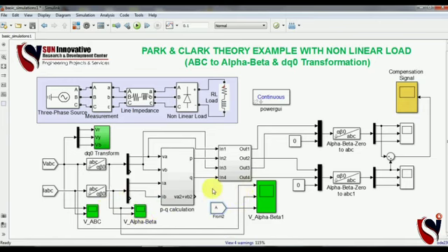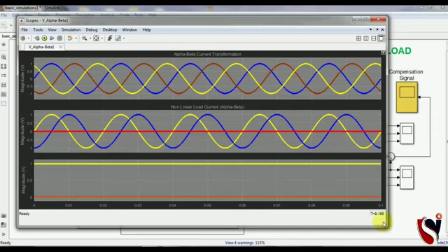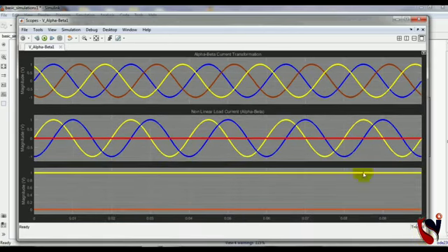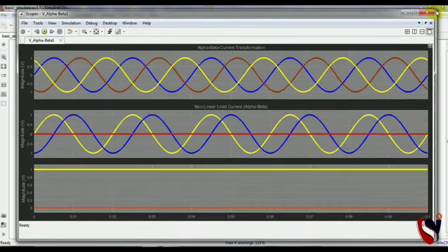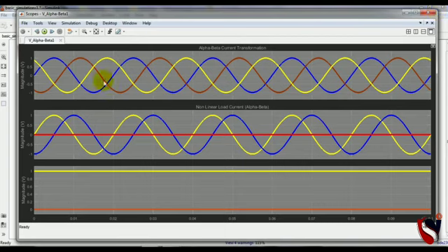This is the final graph of our video: the first graph is the 3-phase system, and it needs to be converted to the 2-phase system. Here you can see the voltage signals, and you can see the red line, the 3rd phase, becomes 0 here. So first this 3-phase system is converted to the 2-phase, and then to DQ.